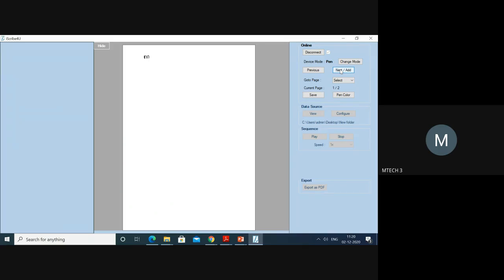So it becomes m1 dot. Okay, so directly we'll write m1 dot. m1 dot will be equal to what? P1 minus P2 by R. Okay, that will be equal to C1 plus C2 into dP2 by dt. Okay, so rearranging, P1 minus P2 is equal to R into C1 plus C2 dP2 by dt. Okay, right. So therefore we'll write P1 is equal to R into C1 plus C2.